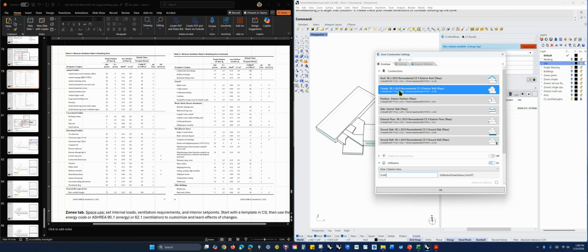Also, let's say we have a really well insulated building, but with a bunch of gaps in it, so air is moving through and we're losing or gaining heat in the winter or summer that way through the building envelope. That will also have a large effect on our energy use and therefore our peak load. So this number is very important. Okay, so that's the envelope and infiltration.